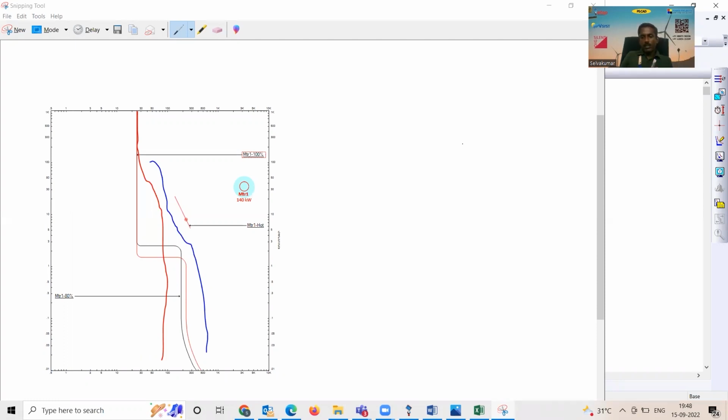What is to be considered additional in case of a motor fed by a contactor? Nothing else. Contactor plus fuse might be the case, nothing else. No other additional thing which you need to consider. But of course, the fuse should not maloperate during the starting of the motor. That's the only thing you need to ensure. So the rule is quite simple. You should not maloperate during the starting, and when there is a fault, the motor should not get damaged. Before that, your protection device has to operate. These are the only 2 things.